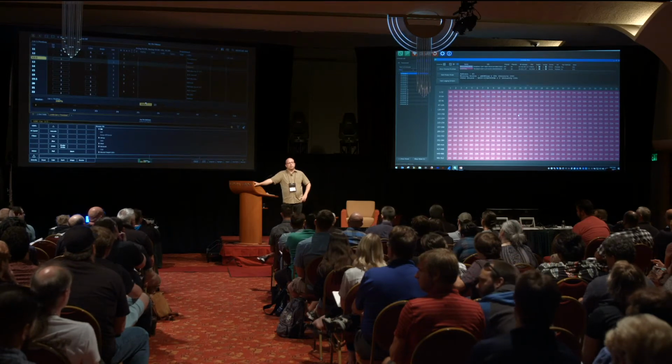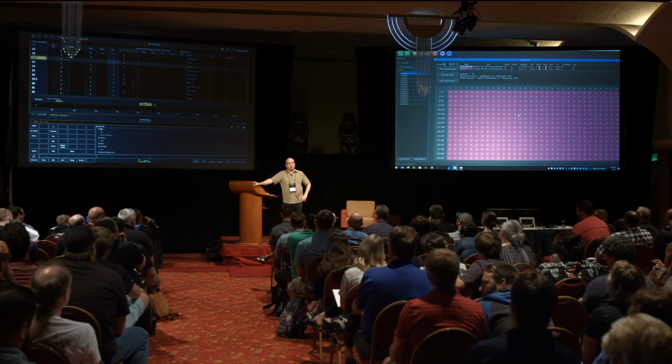It could be. Like I said, my first step, if you're trying to connect your Cobalt and your ION at the same time and something's not working, would be to fire up Streaming ACN View. You should be able to see both of them and see what priorities they have. So if maybe one is set to a higher priority, you'd be able to look at that channel data and see, oh, this is sending higher priority, that's what's going on. So really, as a first step to troubleshooting anything like that, a tool like this can really help you out.